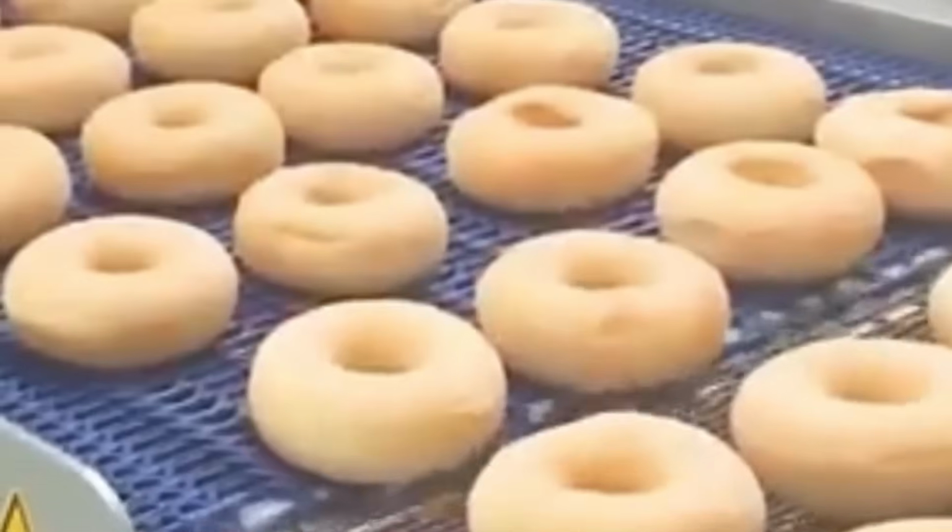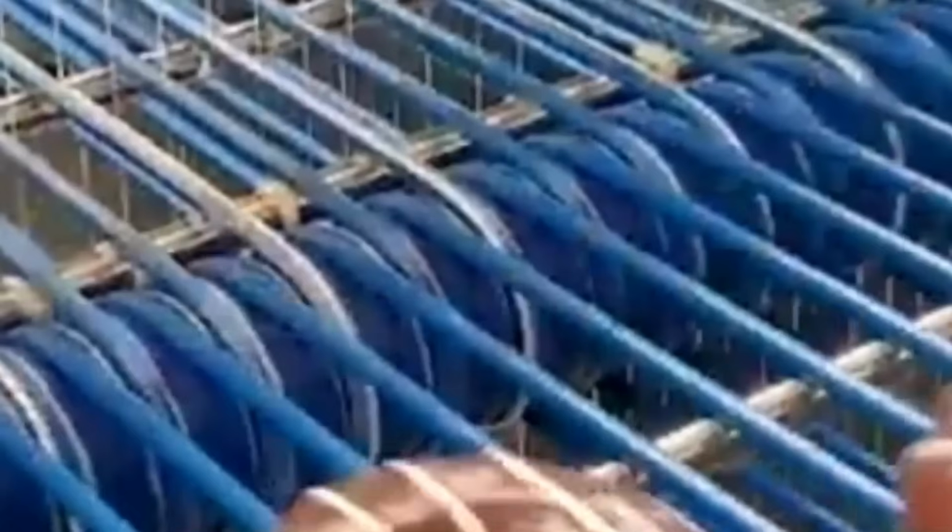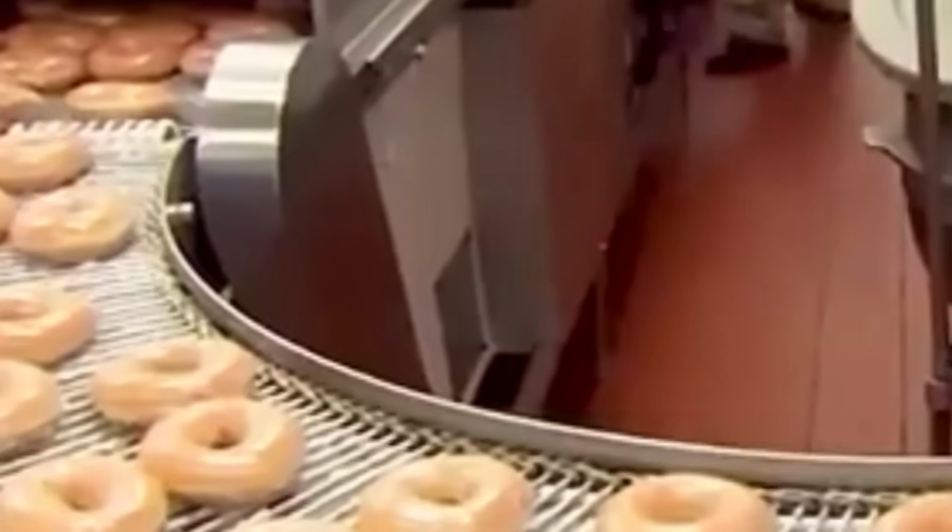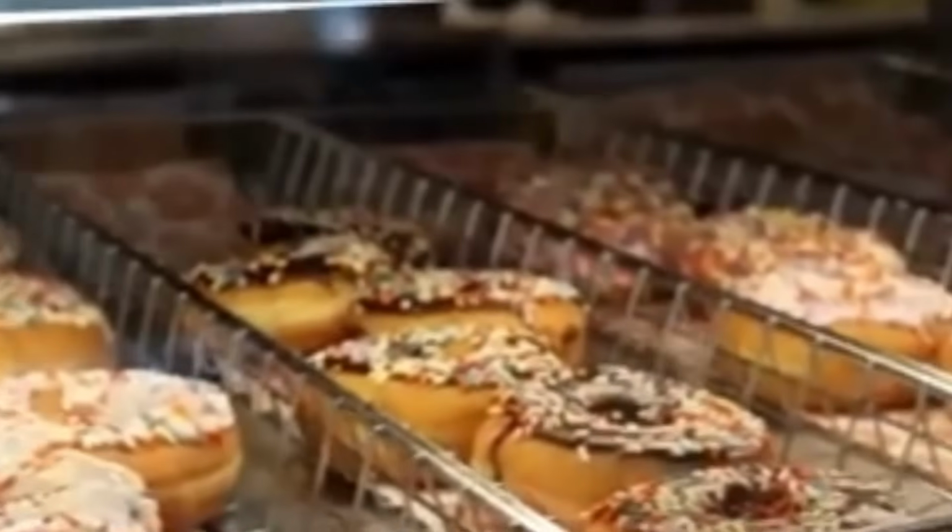Trays are conveyed to the overwrapping station where a film is wrapped and sealed using a heated jaw. Packaged trays proceed to a labeling machine that applies product and date information. Donuts intended for retail stores are stacked into crates by a pusher arm. Crates are conveyed to a loading dock and stored in temperature-controlled bays before transport. Crate movement is sequenced based on product age to maintain first-in, first-out flow.